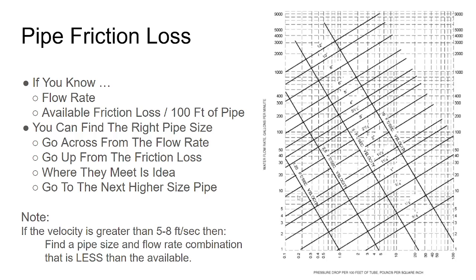Okay, there are friction loss tables. Friction is a little bit like stress in that in many cases it always acts the same. So if I have a pipe that's a certain size with a certain flow rate going through it and it's a certain smoothness or roughness, I'm going to get the same friction loss in every 100 feet of pipe.